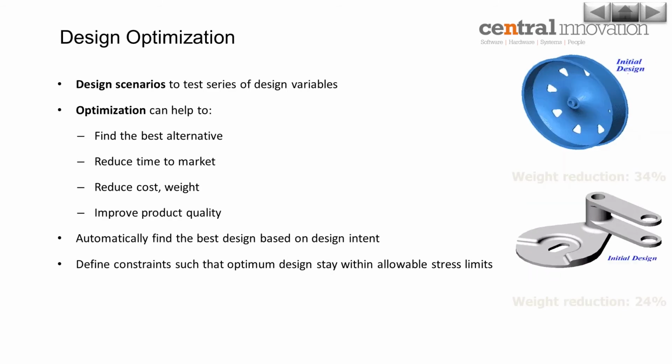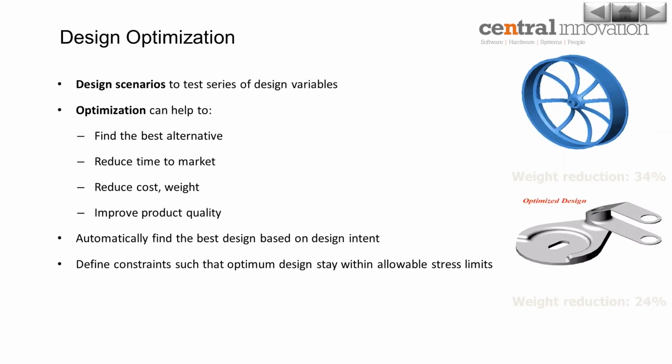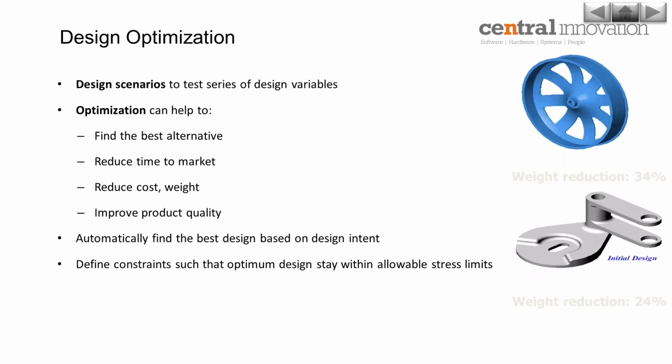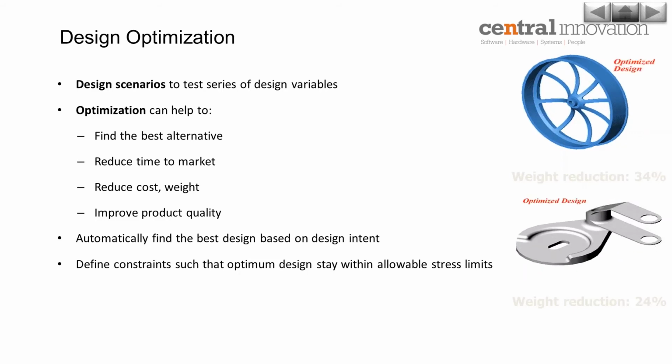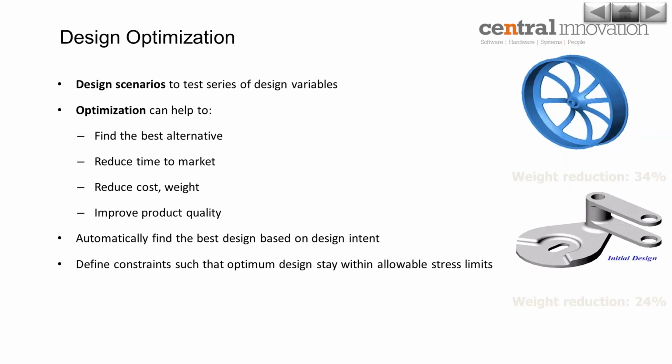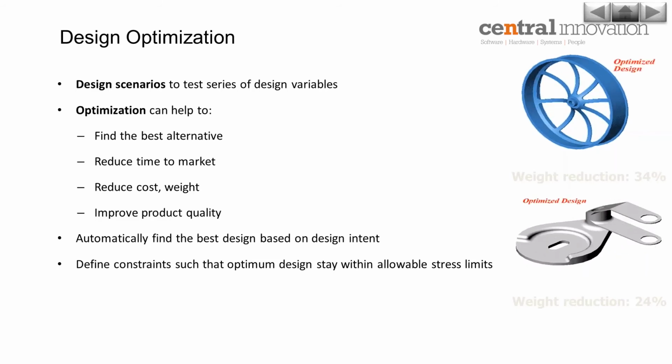As you can see in the graphics on the right-hand side of the slide, I have that alloy wheel. When you perform the design study with optimization, it will try to reduce the thickness of the alloy, and it will check whether, when it changes the thickness, it can maintain the design constraint and stay safe within that limit.